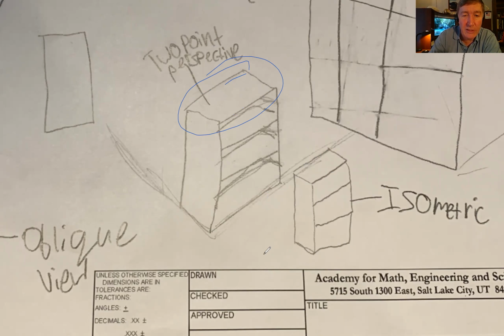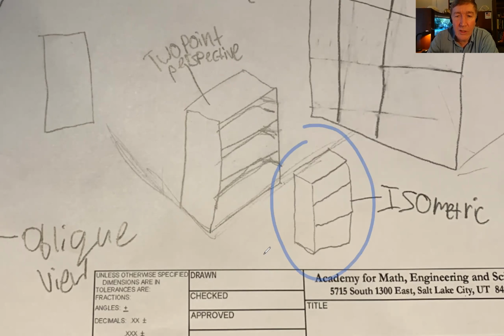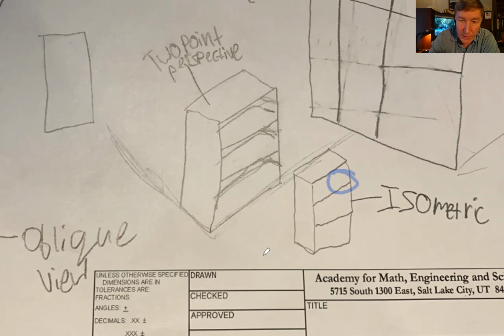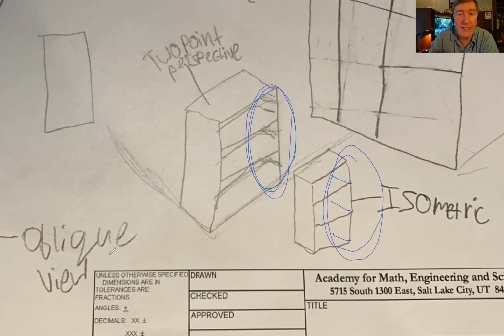So let's look down here at this drawing that they've labeled as the isometric drawing. I'm assuming that this line and this line here are parallel to each other, so I'm going to say, okay, good with that. Do you see a problem over here in the corners? Those lines that I said the first person needed to have, those lines are missing. They put the lines in up here, but for some reason they left the lines out down there. So that's not too good.